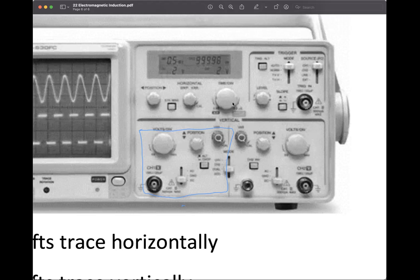So you adjust left to right. This time base doesn't change your frequency, but it changes the display, the scale of your time axis, to become squeezed more together or lengthened. Is that clear? So this is how the CRO works.